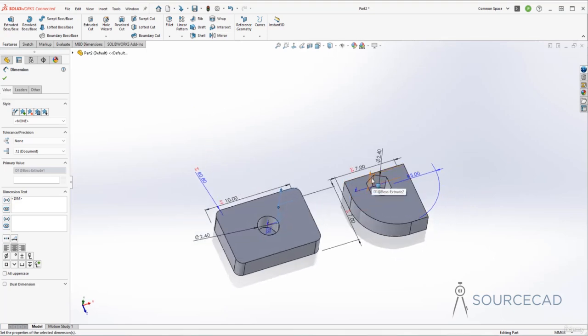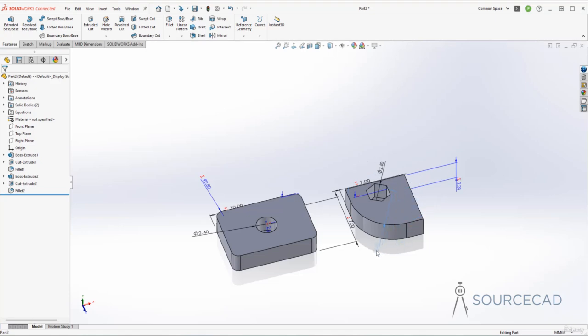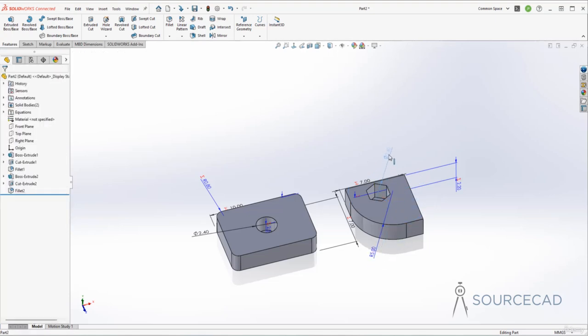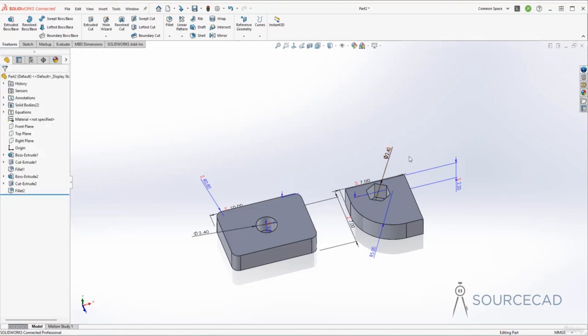But now here, if I just pull it out like this one, that's an equation. But this radius, as you can see, the fillet radius is not an equation. And so is the case with this one. This circle radius is not an equation. Now let's link these two. As you can see, this is 2.4 and this also happens to be 2.4, which is quite equal, but still they are not linked. If I change any one of these parameters, it's not going to change the second one. So let's try doing that.